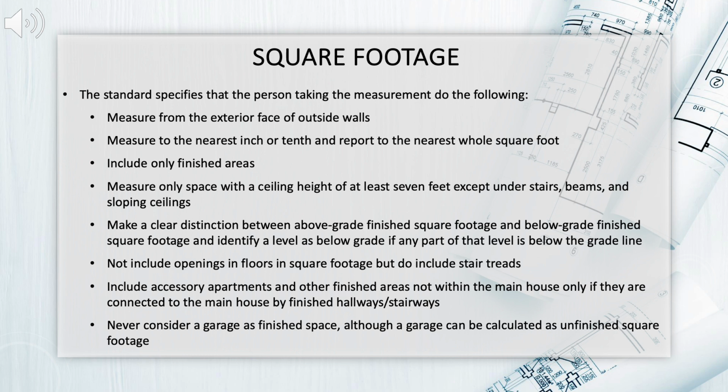Do not include openings in floors in square footage, but do include stair treads. Include accessory apartments and other finished areas not within the main house only if they are connected to the main house by finished hallway stairways. Never consider a garage as finished space, although a garage can be calculated as unfinished square footage.